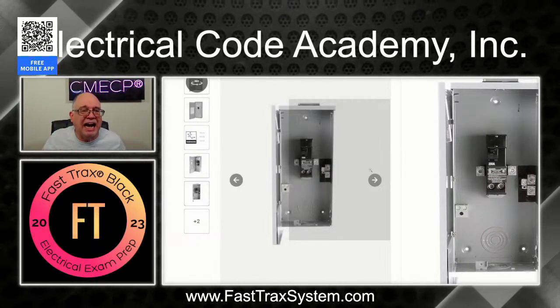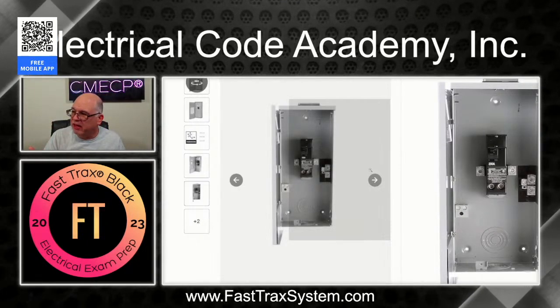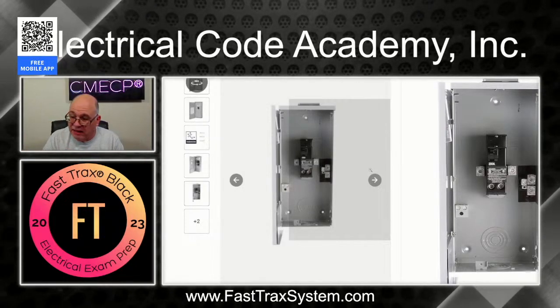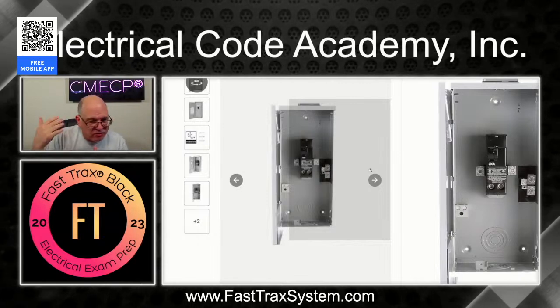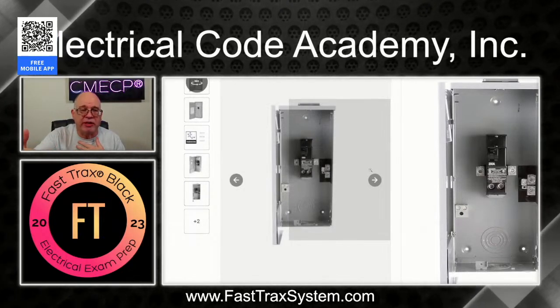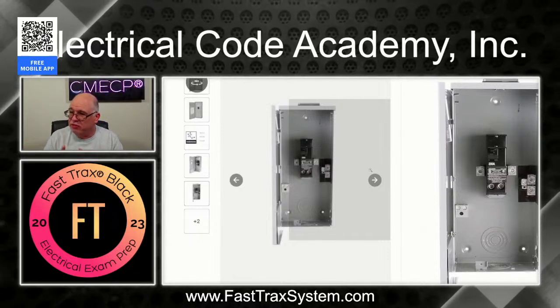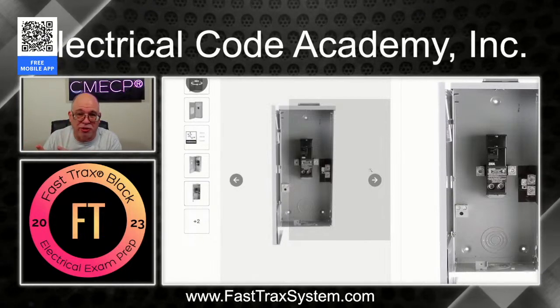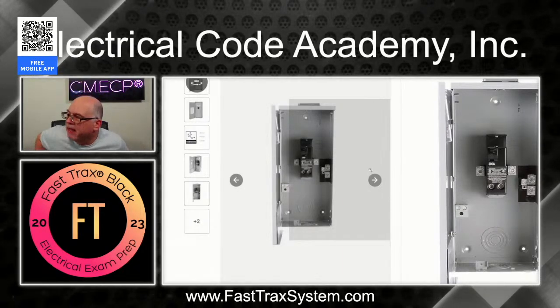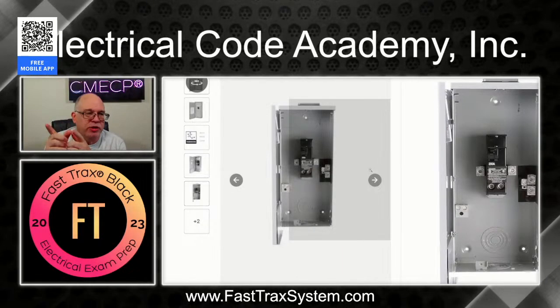This is an option that I would go with. I'd install this on the outside, turn it into a feeder, and I can put my panel anywhere I want inside that dwelling. If they still want it on the other side of the wall, that's fine. But I don't have a limitation on how far my feeder can go. But I do have limitations on how far service conductors can go inside of the building, okay? 230.70(A)(1). So at this point, this is what I would do, right?